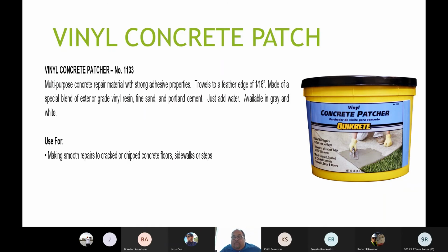So first off was the workhorse that we've had forever, and you guys have sold buckets and pails and bags of this. It's called vinyl concrete patcher. It does not need bonding adhesive or fortifier. There's a powderized version of that in the mix. What this is used for is repairs of cracks, sidewalks that a tree root has grown up, anything about a half inch, 10 square feet.